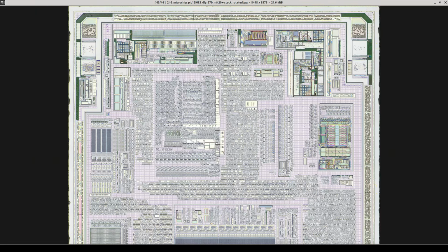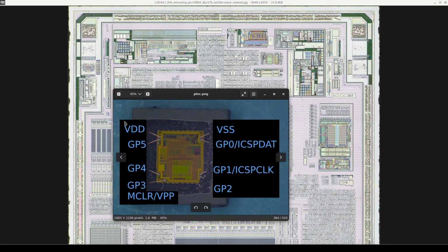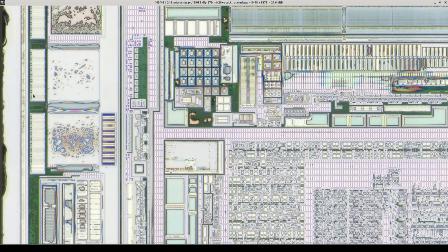Next, looking at the I/O pins, and again going back to the device pinout, we've got the VDD pin here, and note around here we've got protection diodes to the outer ring here, but not on the inner one.